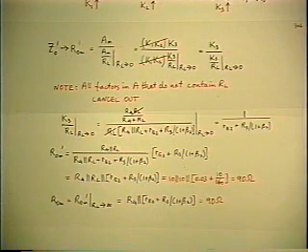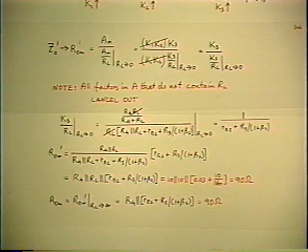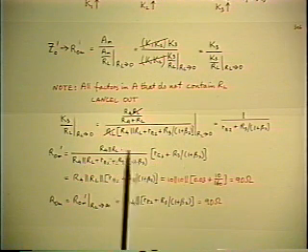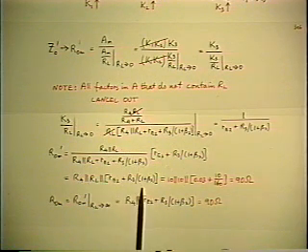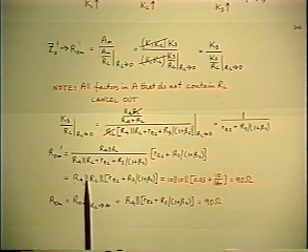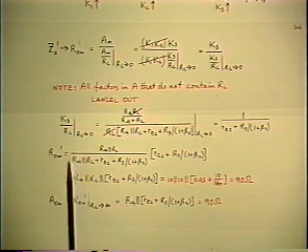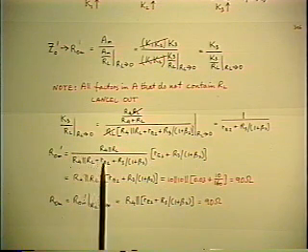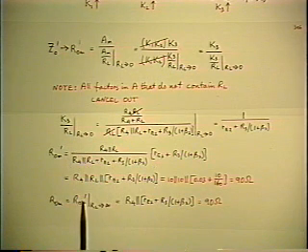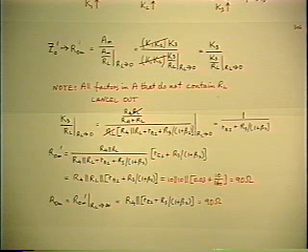Well, you can lower the entropy a little bit by recognizing, in a rather obscure form, product over sum, which is the parallel combination of R4 and RL already in the parallel combination, times the square bracket, divided by R4 parallel RL plus the square bracket. So you can condense that down to the triple parallel combination.